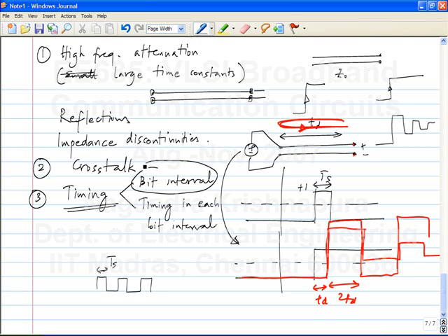What is another problem with this? No, that is all like more detail. I am talking about more of economics type of thing. It's the same thing as initially, before I said that I can't use two wires if I want to double the data rate because it's too expensive. That is always an option. So here it's the same thing, right? To transmit the same data reliably, I have to send both the data and the clock. So that may be too expensive, so maybe I choose not to do that. So if I have some way of recovering the clock from the data, I would prefer that compared to sending the data separately. Okay. So all this is a question of whether it makes sense economically in a particular system or not.